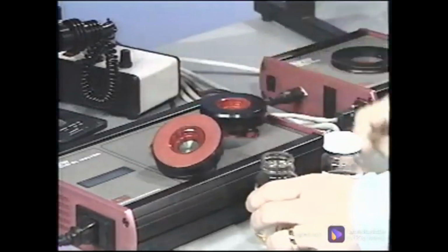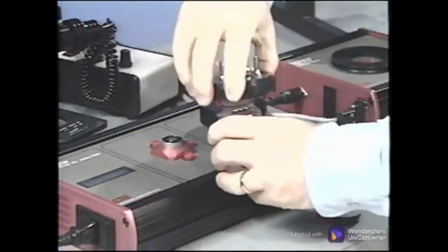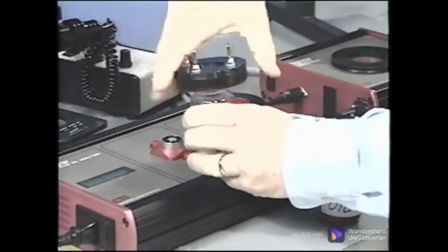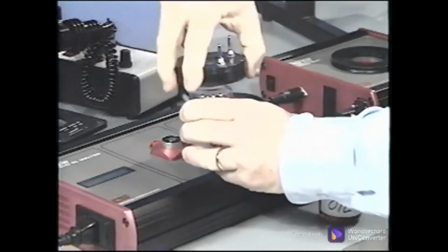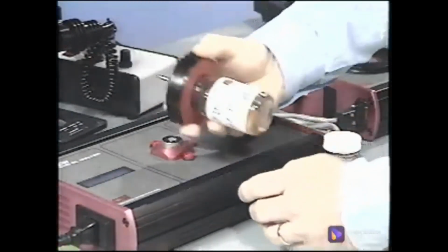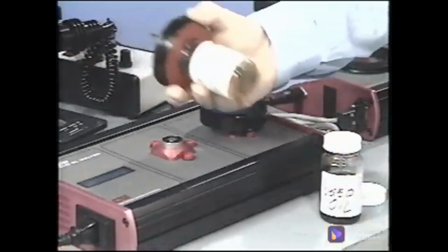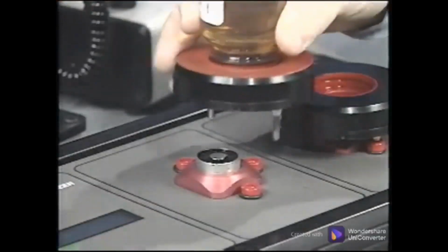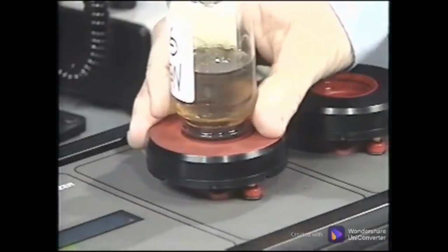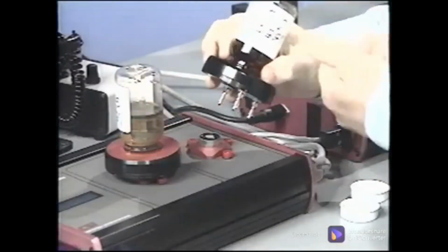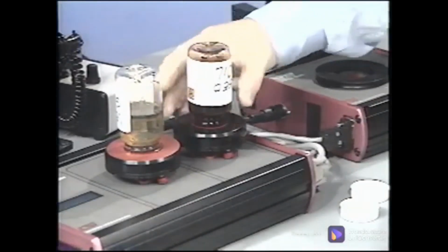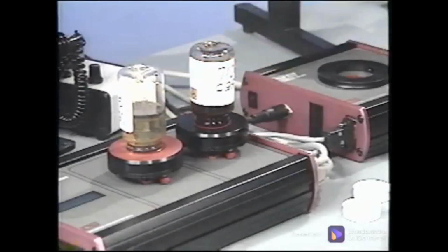A full test must be run on the new clean oil as well as the used oil because, unfortunately, the new oil samples sometimes have dirt and water and must be inspected periodically to ensure harmful contaminants are not being introduced into the system. When the new lube is tested, it is recorded in a database for easy retrieval and comparison with future samples. After proper setup, used oil samples are well shaken and tested for 500 seconds or about 8 minutes, comparing the results to a reference oil.